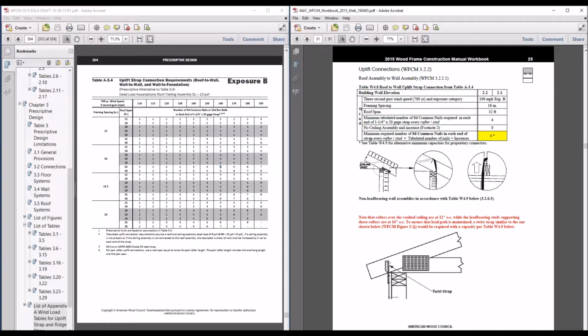If they're coming across the top of the truss or whatever rafter, I know this is showing a truss, but it could be across a rafter, you've got load paths so that those are coming down into the sheathed side of the assembly, and you're not creating any kind of eccentricity here by putting that strap on the inside.